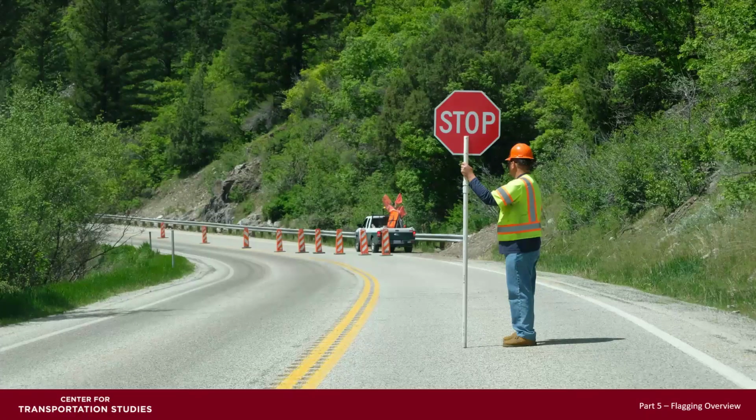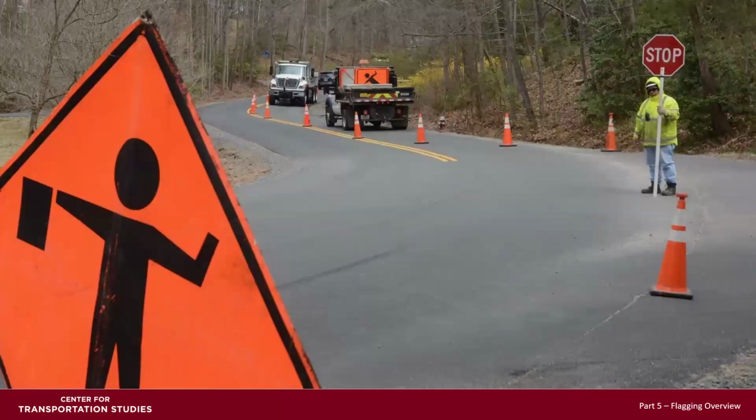Once again, standing in the lane with the stop paddle shown, not facing traffic, and possibly in a bad sight location. In this case, the flagger is standing off on the shoulder of the roadway, but is probably too close to the flagger ahead sign in this location. And there's an intersection that they're standing in, if someone approaches there and they're not watching that.